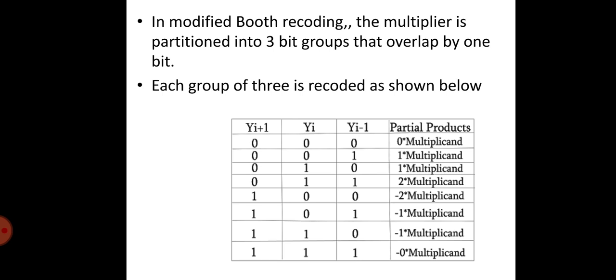While the multiplication with 0, 1 is equivalent to an AND operation, multiplying with minus 2, minus 1, 0, 1, 2 requires a combination of inversion and shift logic. The encoding can be performed on the fly and requires some simple logic gates.